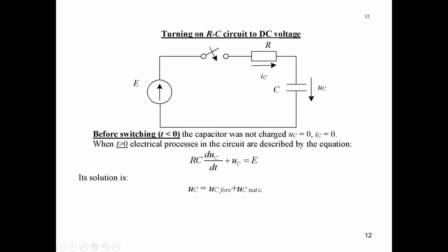And in such a case you should remember that there will be current through the inductance in steady state regime, because we will not have here DC, we will not have here steady state constant voltages and currents. The derivative will not be equal to 0, so we will have current through the inductance.